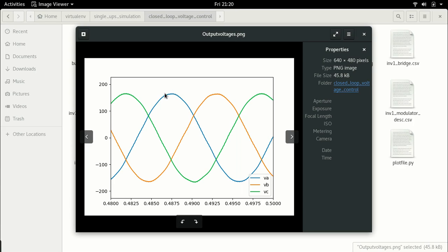So now we have not only a three-phase sinusoidal set of voltages, but we also have them regulated with respect to magnitude. So this is a completely regulated, controlled voltage source. This is the advantage of the UPS. We have now done a two-layer control, that is an outer voltage control and an inner current control, to be able to achieve this. Alright, so I think this is it.